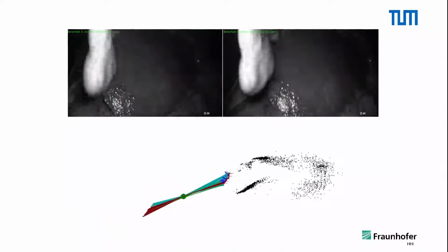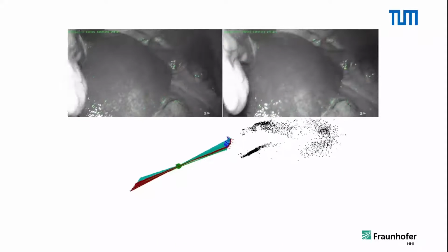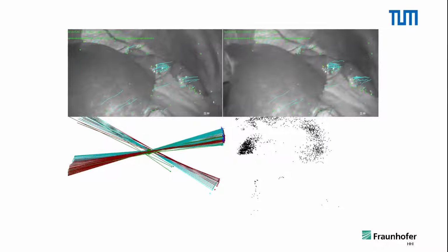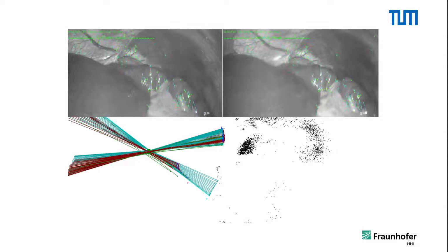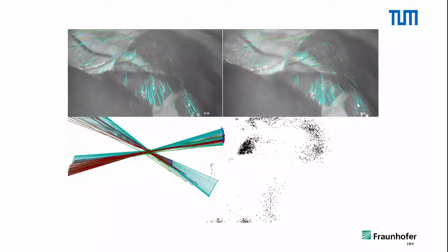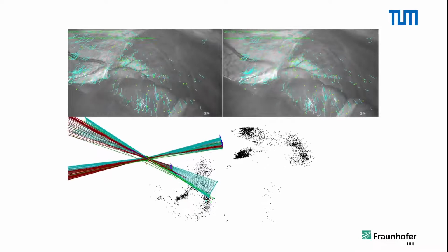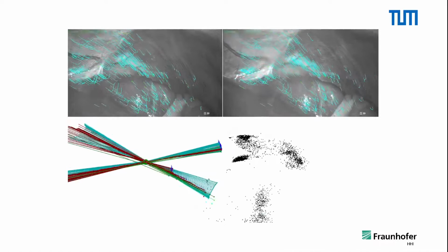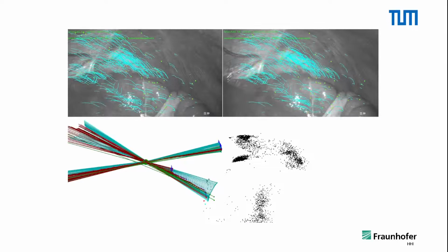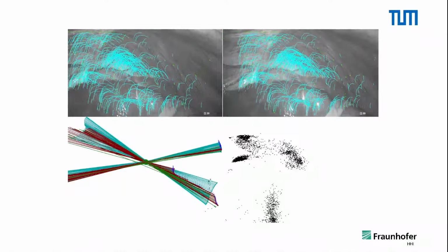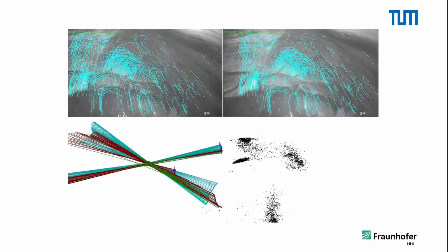Now, the image quality was really low, and every SLAM algorithm loses tracking. Most importantly, our algorithm now relocalizes the camera without finding descriptor matches or conducting image alignment, as it is done in direct methods. Furthermore, the huge dynamic part was filtered out, since it was not aligning with other information from IMU or motion constraints. The map points move as soon as their extraction frame is optimized. After optimization, the map is realigned and the geometry is observable.